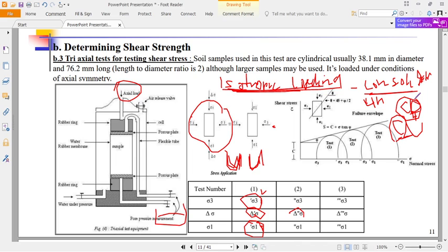For such a material, you record this, you increase this, then you apply the axial load, then load 2. Then you repeat it the third time through the same procedure, so you come up with enough data. How do you plot? You plot sigma 3, which is our minor stress, then also you plot sigma 1, which is our major principal stress. Then you get the radius, then you can draw this circle. Then you repeat it for this other circle, and again for this other circle. Then you draw a straight line. That straight line is a tangent to these three circles of stress.